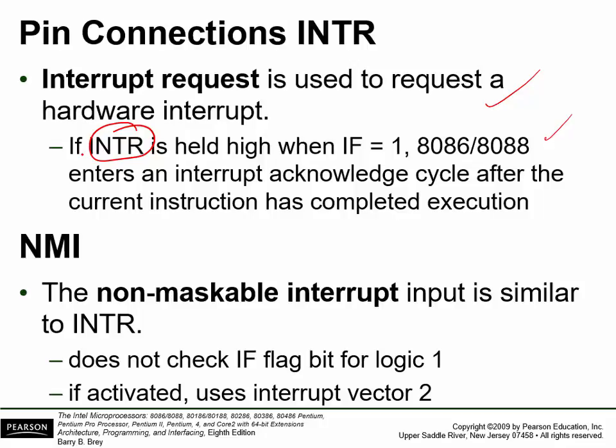A security guard, for example, in a building may walk around the mall once an hour and check to make sure all the doors are locked. But at the same time, there are alarms on each of the doors. So if somebody opens the door, the alarm goes off. That's an interrupt. So you have either polling or interrupts. An interrupt is like an alarm. Polling is where you're going through and physically checking each activity. So you'll get into those interrupts, and we'll talk about those in more detail. But there's a pin called interrupt request. There's also another pin called interrupt acknowledge, which is not listed here.